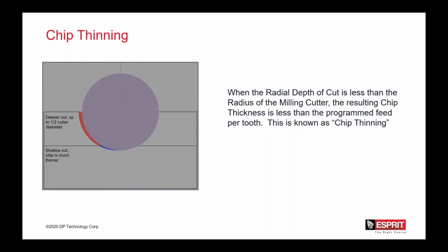With a shallower cut, in order to maintain the proper chip load, the cutter can be sped up using speed factors or feed rate multipliers. We can increase it typically by as much as 8 times your typical feed rate during these chip thinning milling processes.